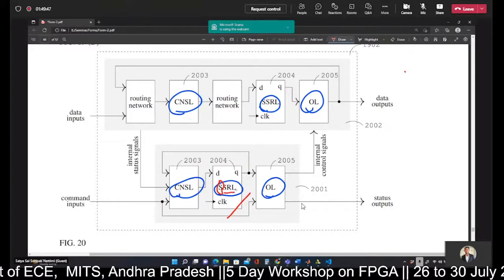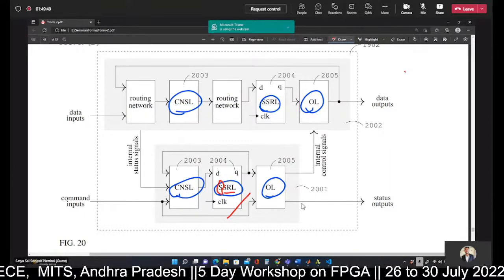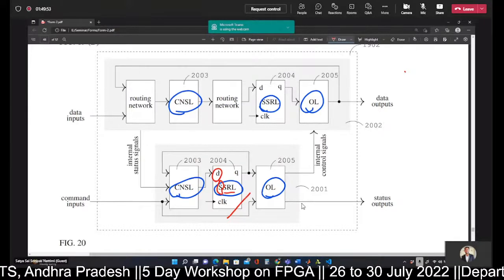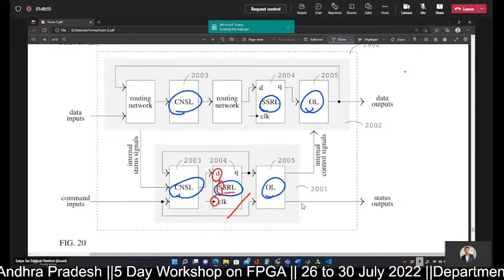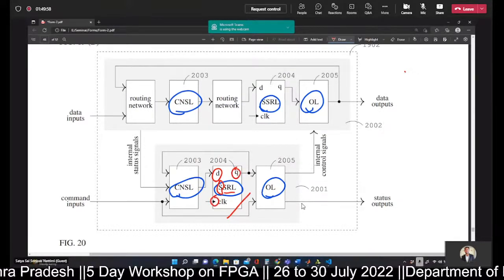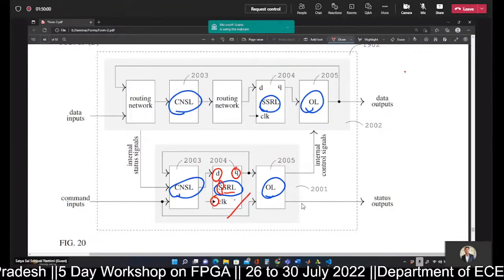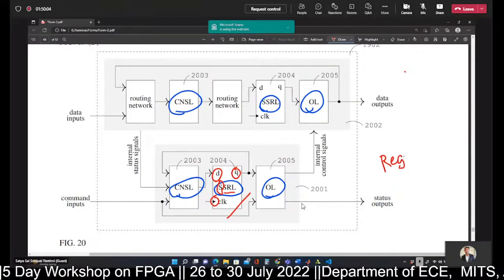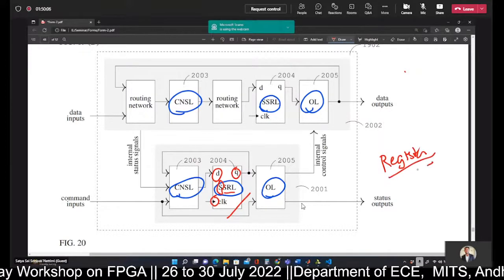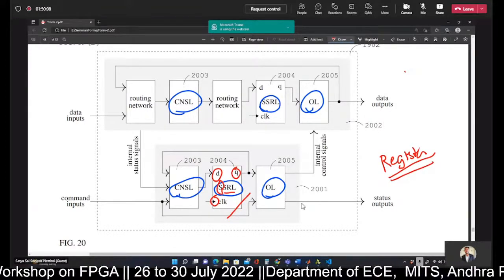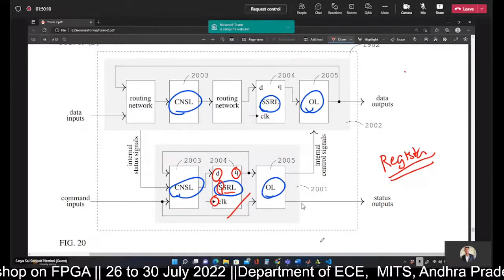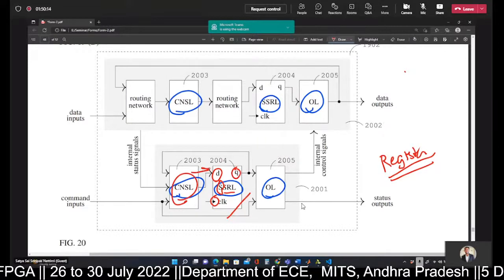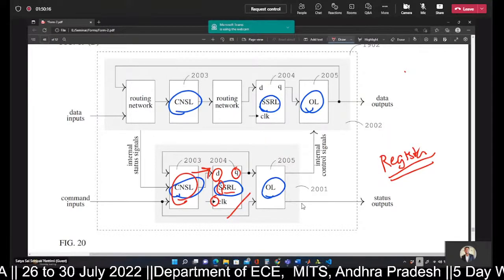State register means just like a register which stores the data on arrival of a clock edge and outputs the data. So we need to declare a few registers in our design, and combinational next state logic is there, that is driving the sequential state register.